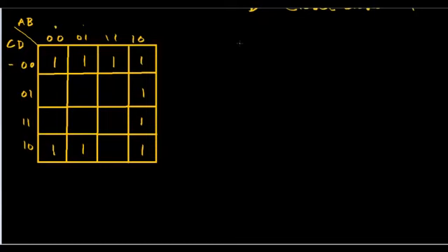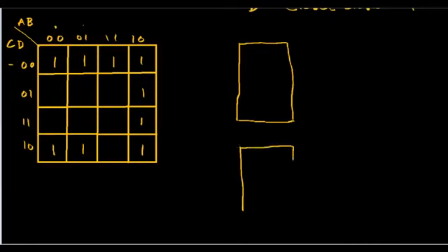So there are a couple of different ways to create this using 4-to-1 multiplexers. But because we're using the 153, we're a little bit limited because both inputs have to be the same. Okay, so I'm going to use A and B as my inputs for both of these multiplexers. And I'm doing that because this K-map is set up like that.